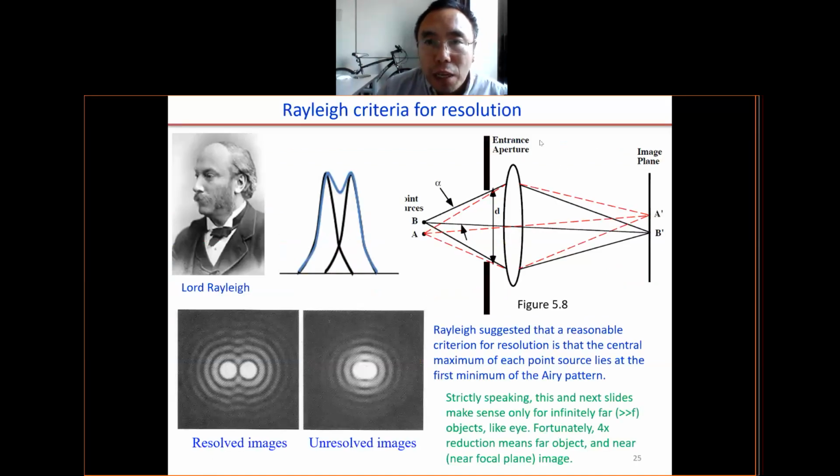So previously we talked about a Rayleigh criteria. For the Rayleigh criteria, we have this light profile. So you can consider this one is MTF. So this is the I max. So this one is I minimum. So this is the Rayleigh criteria. But the Rayleigh criteria does not consider the property of the resist.